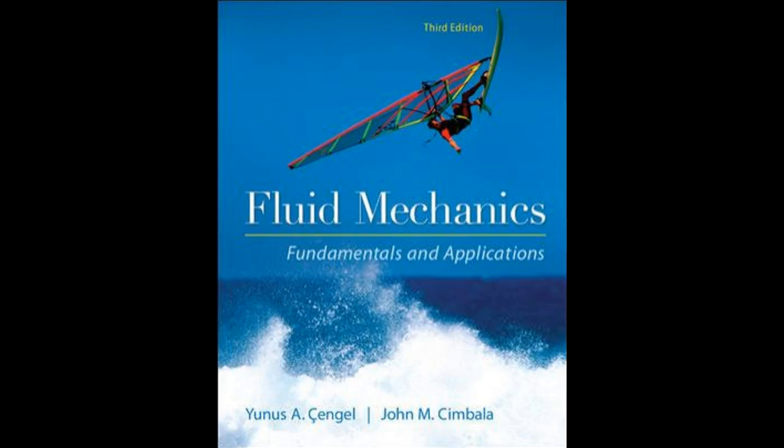We choose the control volume to be fixed between sections 1 and 2 of the flow field. Both 1 and 2 are normal to the direction of flow. At some initial time, t, the system coincides with the control volume, and thus the system and control volume are identical, the greenish shaded region in Figure 4-55. During the time interval delta t, the system moves in the flow direction at uniform speeds V1 at section 1 and V2 at section 2. The system at this later time is indicated by the hatched region.